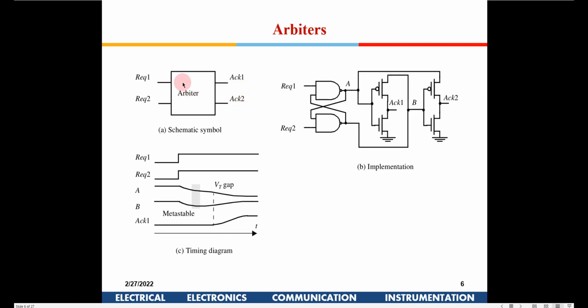It will process request 1 from one core and give that data to it, and when the acknowledgement signal goes, the data will be enabled, and that core will accept that data. Subsequently, once it is accepted, the request signal will go down, and then the second one who has made a request will be given the data.